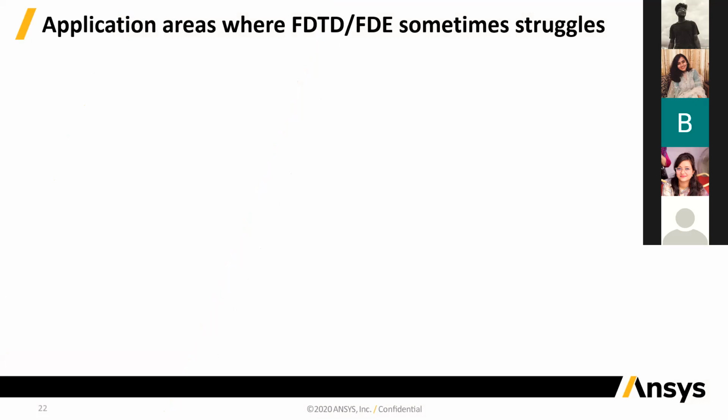Yeah, so I think this question is very timely for the slides that we just saw. So yes, with FDTD, you can simulate cadmium telluride multi-layer solar cells. But like I mentioned, with FDTD, you are going to capture the optical considerations, right? So you can design your device and try to make sure that maximum light is getting absorbed in your layers.